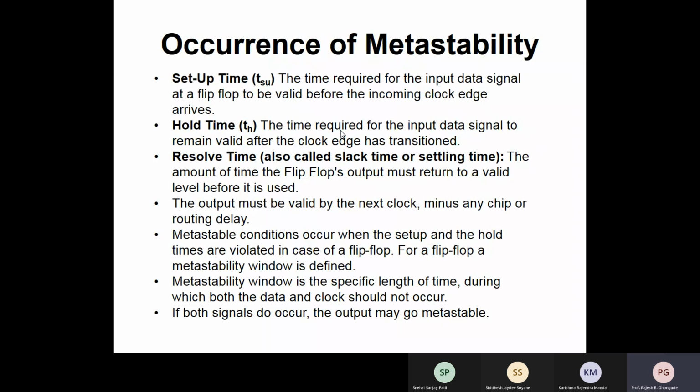How does this metastability occur? For that, we have to understand some important terms related to the flip-flop. One of the important parameters is the setup time, TSU. It is the time required for the input data signal at a flip-flop to be valid before the incoming clock edge arrives. We should never say that as soon as the clock edge has arrived and the data is present, it will work properly. It may not, because the data signal has to be there prior to the incoming clock edge, so there is some time before which it should be stable.